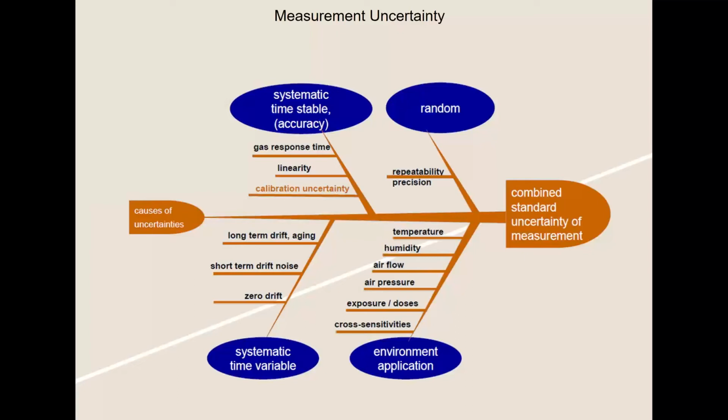Maybe you want to use a video-based flame detector, right? It's looking at the actual behavior of the flame in the video. So it's not using any of the UV, IR, triple IR standard type of flame detection. It's actually looking at the behavior of the visible flame to determine if there is a flame.